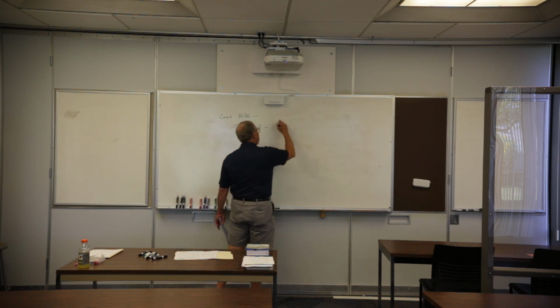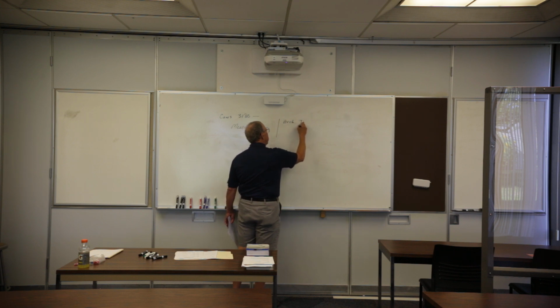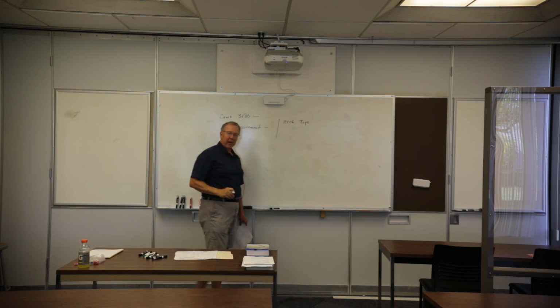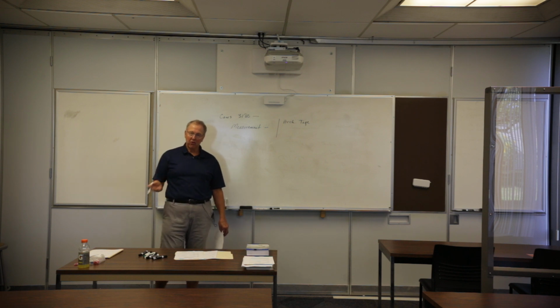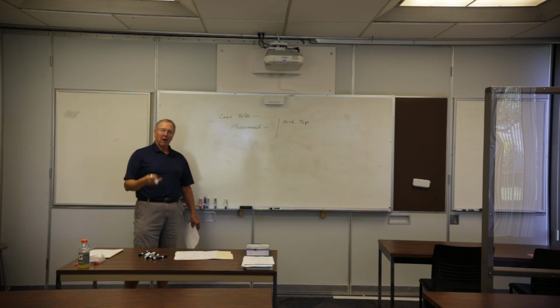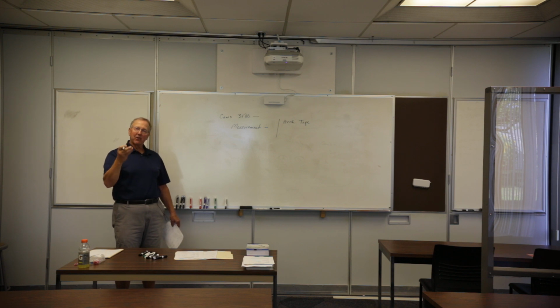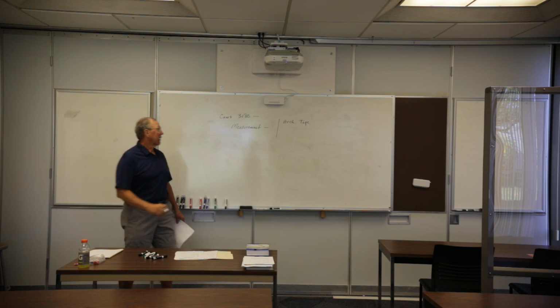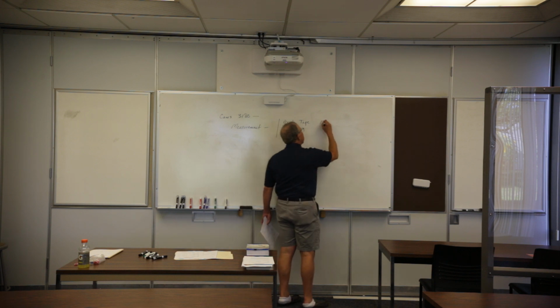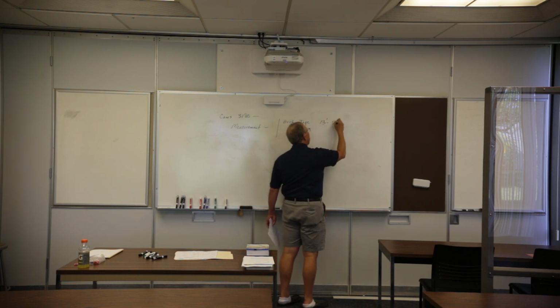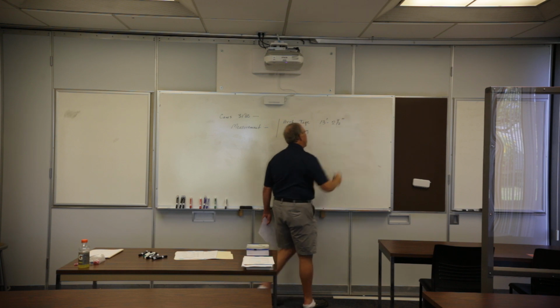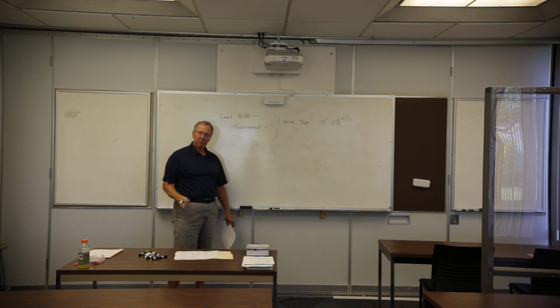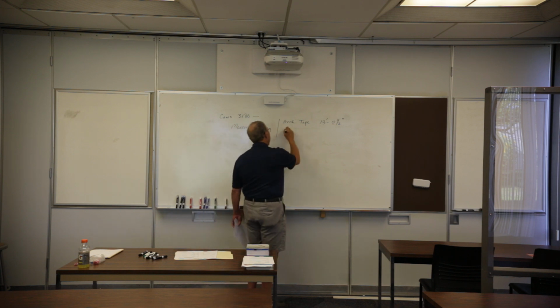Depending on where you work and who you work with, you're going to have an architectural tape. That's like a carpenter's tape. It comes in feet, inches, and fractions. 14 feet, 7 7/8 inches. 13 feet, 2 1/2 inches. That's an architectural tape. So you're going to have to be able to read the tape. We've got an engineer's tape.